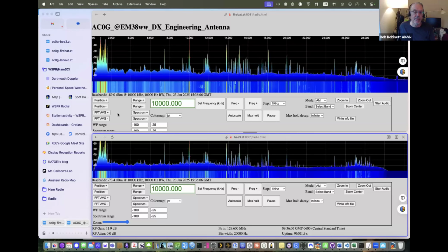But no, they don't make them in that form. The switcher manufacturers don't. So you have to actually build one. You have to take a Meanwell, put it in a box, get a couple of Corcoms from wherever, and then wire it all up. And that's a lot of trouble. But I think for our sites, one of the hopes was we could run everything off of 12 volts. But then you have to change down to 5 volts for some.